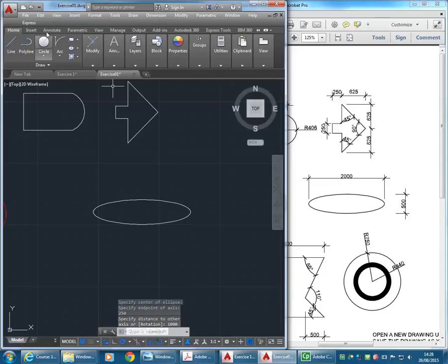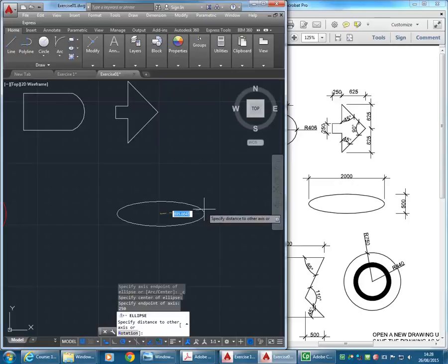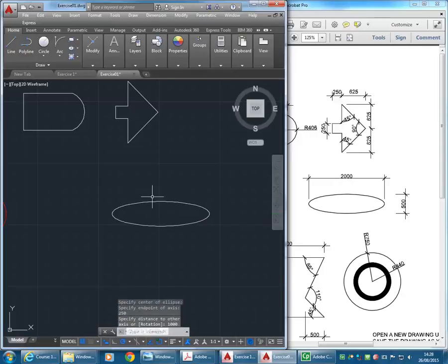But make sure, sorry, I wasn't careful there. Just do that again. So make sure it's going in a straight line. So again, up 250, that was okay. But then across, there we are. So you've got to make sure it goes 0 degrees, not down, because that's where it'll measure the distance to. So it has to be in that angle 0, and then 1,000, so that's done.